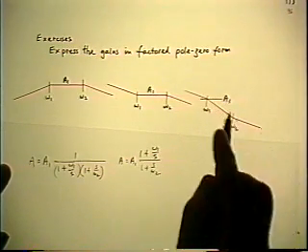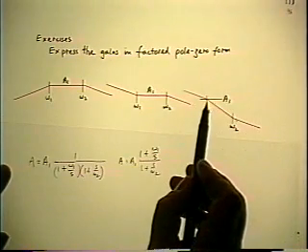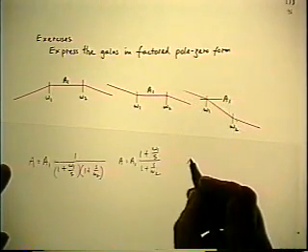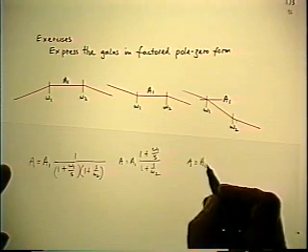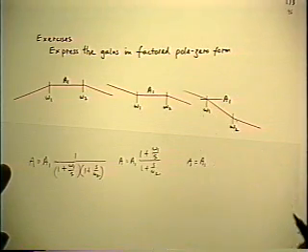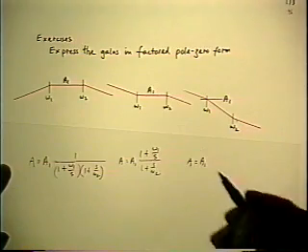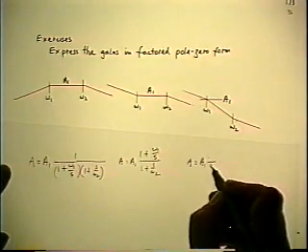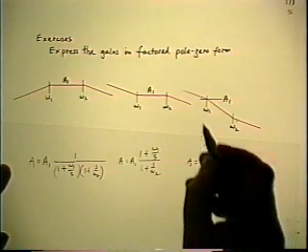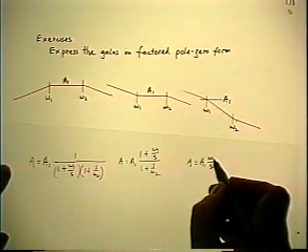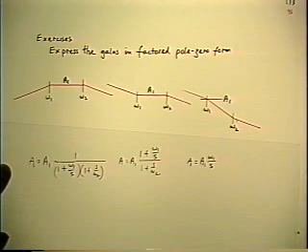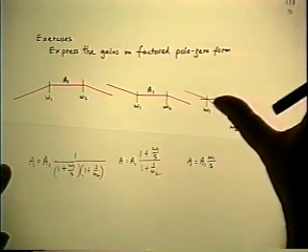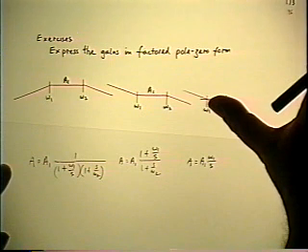So, forgetting the second asymptote for the moment, the first asymptote can be identified as A equals A1 at the frequency omega 1, but it's already on the slope. So the S term is in the denominator because it's a negative slope, and the reference frequency is omega 1 in the numerator. So the equation that I've written so far identifies the left-hand asymptote.